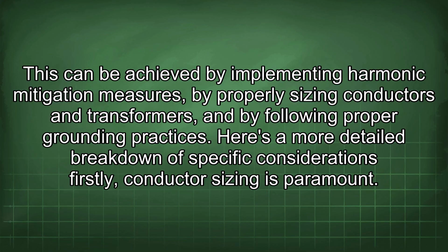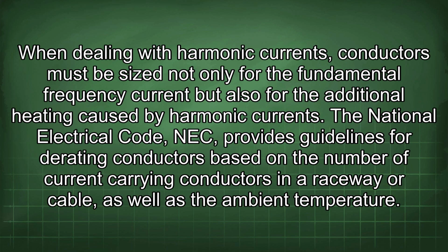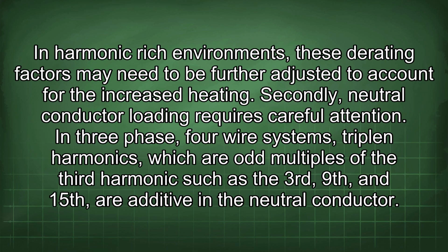Firstly, conductor sizing is paramount. When dealing with harmonic currents, conductors must be sized not only for the fundamental frequency current, but also for the additional heating caused by harmonic currents. The National Electrical Code, NEC, provides guidelines for derating conductors based on the number of current-carrying conductors in a raceway or cable, as well as the ambient temperature. In harmonic-rich environments, these derating factors may need to be further adjusted to account for the increased heating.